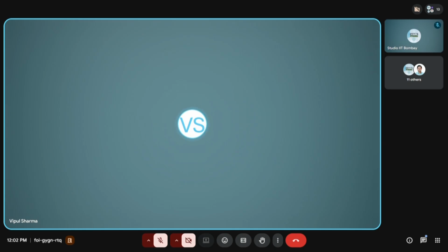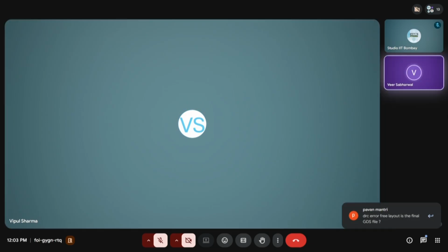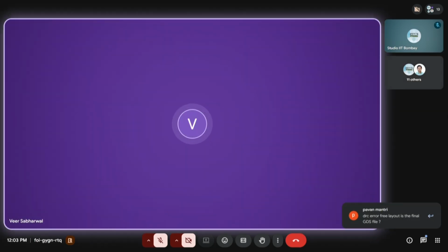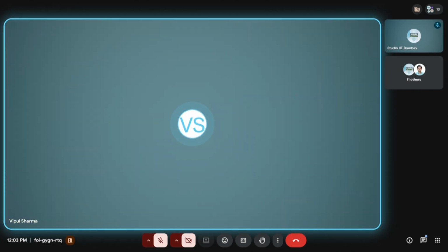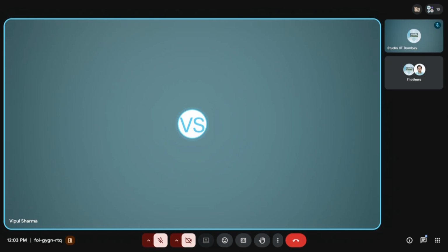Because if this duration is missed, I don't know when you will get the next opportunity to send your design for fabrication. So that's my piece of advice in this case. Sir, exactly how long time do we have till tape out, till the final GDS submission? So that's what I mentioned. By 30th April, by end of this month, you should be ready with your design. When I say ready with your design, you should have a DRC and LVS clean GDS shared with me.